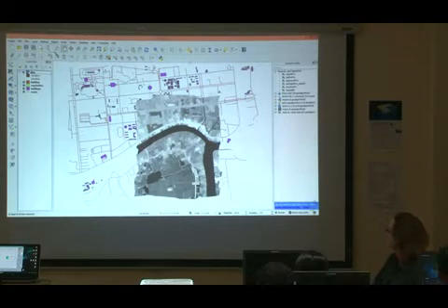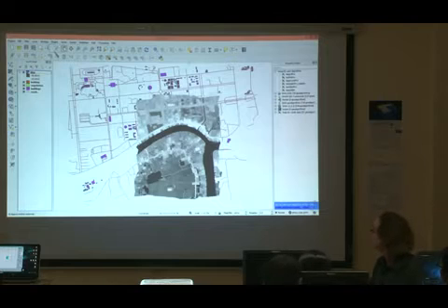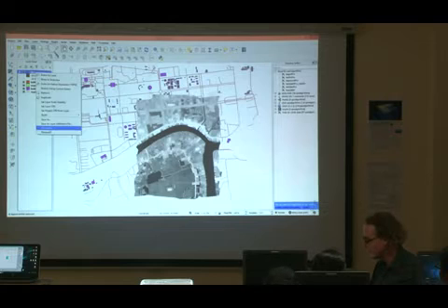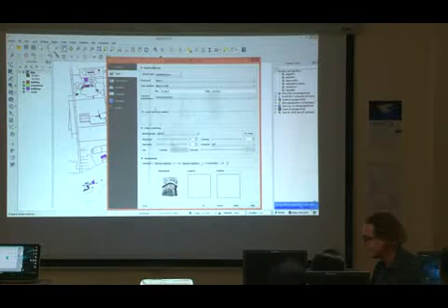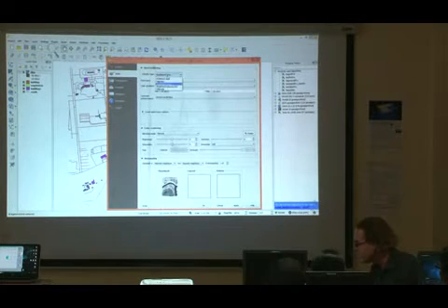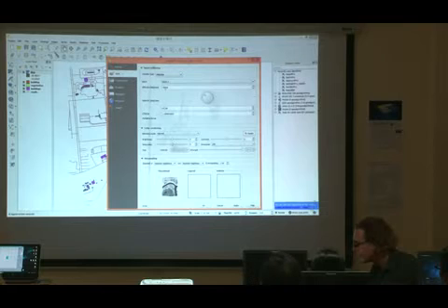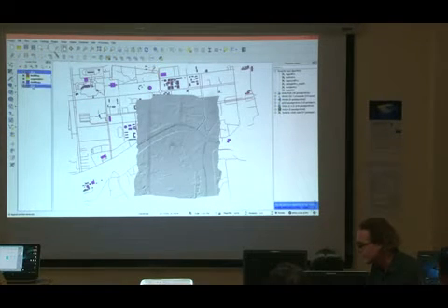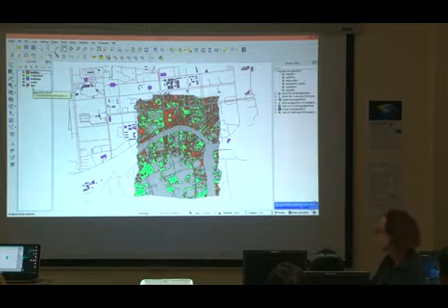So here's my single raster, and now I can give it a different shading, and that's new in QGIS 3.18. I can directly give it a hill shading. Apply. Okay. And I move it into the background. Voila.